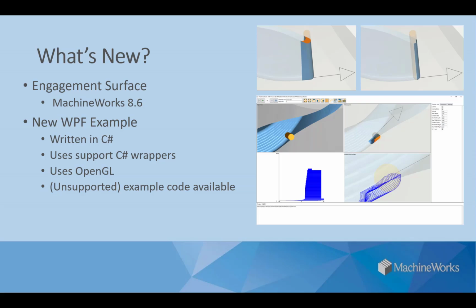So typically when you are analyzing the cutting force on a tool as it's cutting stock, you want to know things like the volume of material removed, the engagement, the depth of the engagement on the left and right side of the tool, etc. And MachineWorks, because it's a polygonal solid model, can give you a full intersection solid of each cut as it happens.